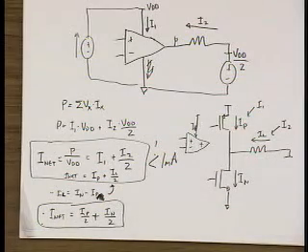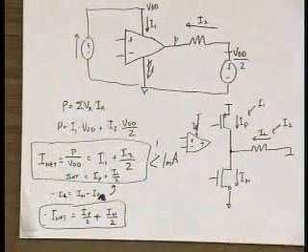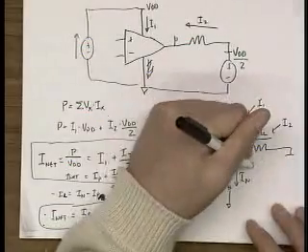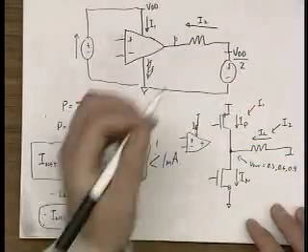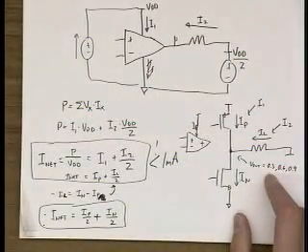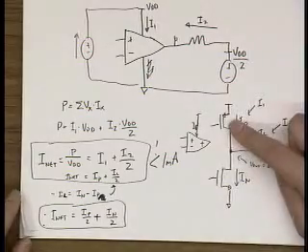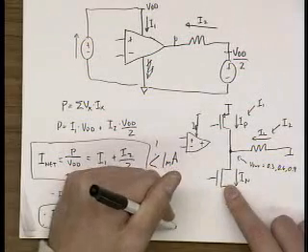And so the thing to note is that, okay, depending on how you implement this, one corner or the other might have, in other words, Vout is going to equal either 0.3, 0.6, or 0.9, okay? One corner or the other of these, depending on your implementation, will probably have the highest net device current. For instance, if the PMOS is a current source, and this is your common source transistor, so it looks something like this.